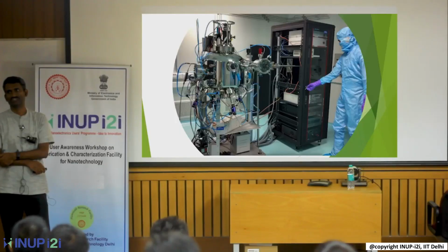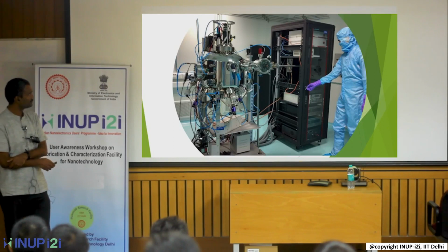For example, if the argon source gas has a lot of impurities, those will become part of your film and change the material properties. So when people report these vacuum conditions, you have to state clearly at what conditions the films were deposited.